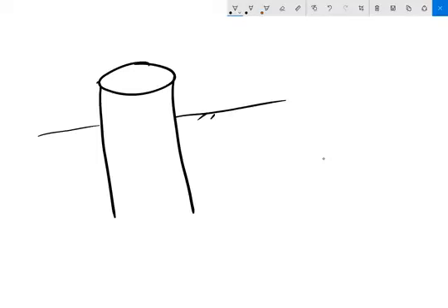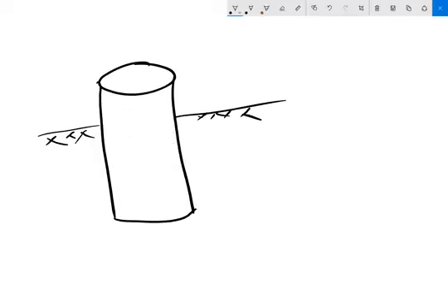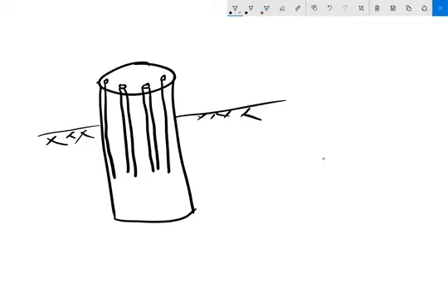this is the ground surface, and I'm building this big drilled shaft in the ground, and I want to know how competent and the integrity of this drilled shaft at the various depths within it. Oftentimes, when we construct these drilled shafts, we'll put these PVC pipes all the way down. And these pipes would extend all the way down to the bottom of the shaft, of course.